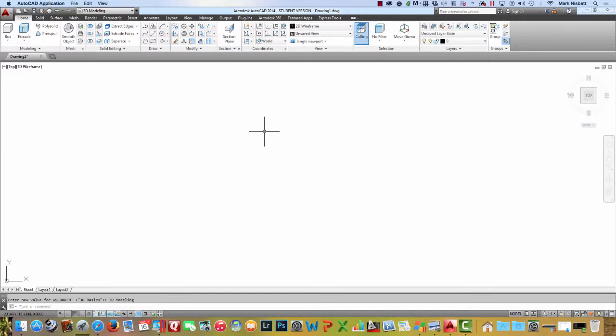So basically at any given time we're drawing in 3D all the time. Basically we're drawing from above. We're looking at our top view. As you can see here in AutoCAD, up here in the upper left hand corner, we're in our top view. This also correlates to something called the World Coordinate System, or the WCS. You can see that over here in our navigation tool. We're in our top view right now. North is up here, south, west, and east. And also right here you can see it says WCS. So currently we're in the World Coordinate System.